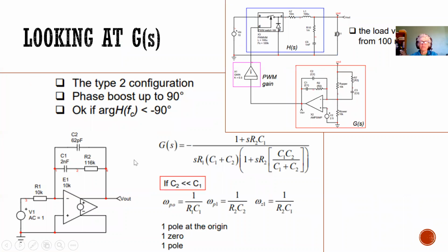In lab, I am guessing that maybe you put a resistor in series with a capacitor. Yes. Okay, so that right there adds a second pole and adds a 0. And so you'll still have a pole, but you can use that 0 to cancel out your first pole.